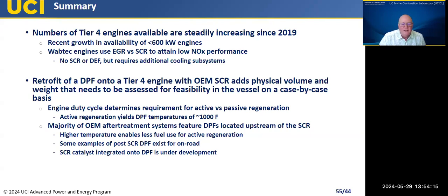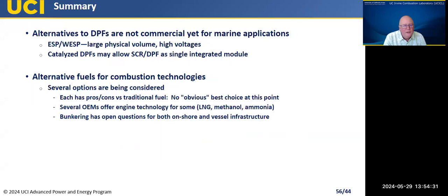There's a lot of questions on regeneration and temperatures. If you can put the DPF closer to the engine, you'll use less diesel fuel for regeneration. All right, but this is an area of active consideration. Next and last. So alternatives to DPFs, not commercial yet.